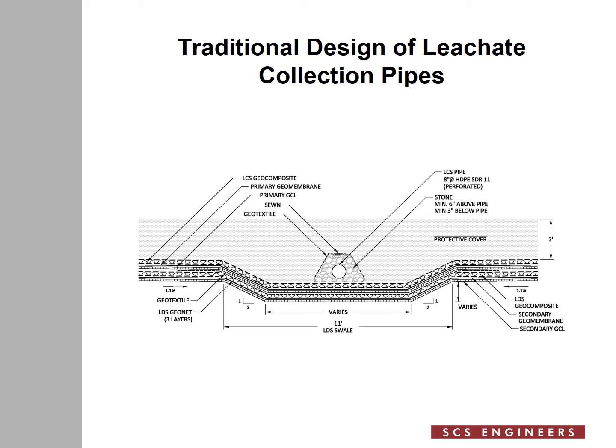I would like you to envision the flow of leachate through the composite getting into the leachate trench, which in this drawing also refers to it as LDS soil, but I will be using leachate trench throughout this presentation. The water in the composite, in order to get to the pipe, would have to come out of the geonet through the upper geotextile component of the composite, pass through the geotextile wrap to enter the gravel, and from the gravel to the pipe.